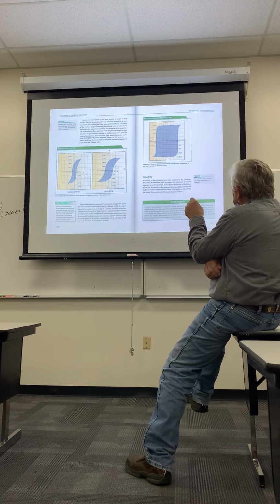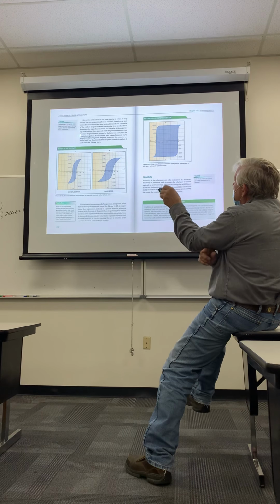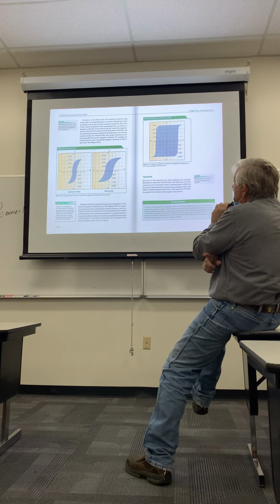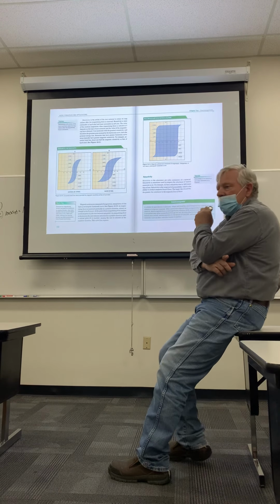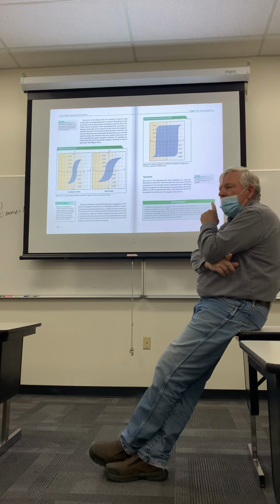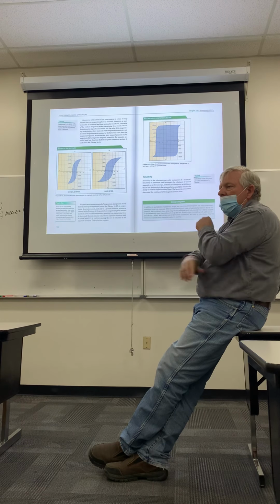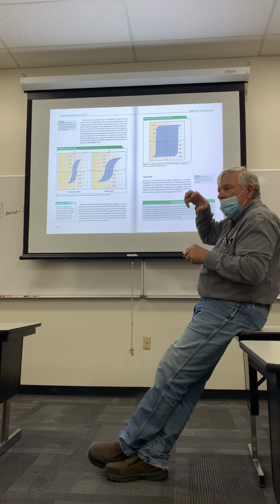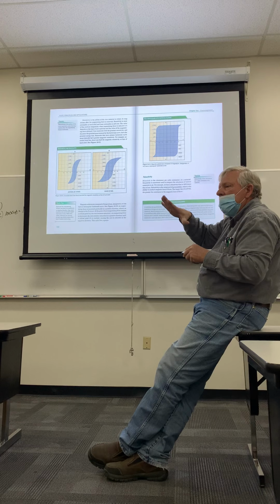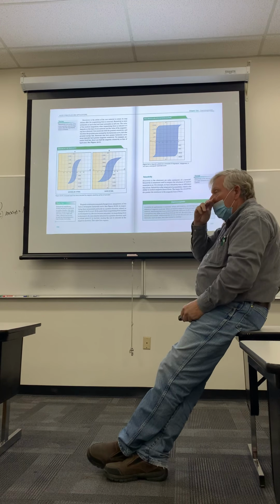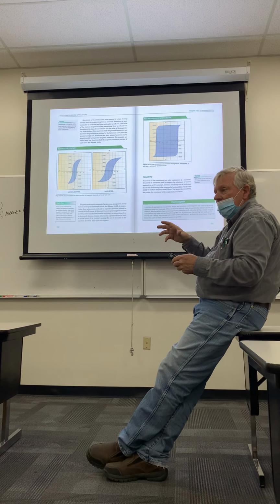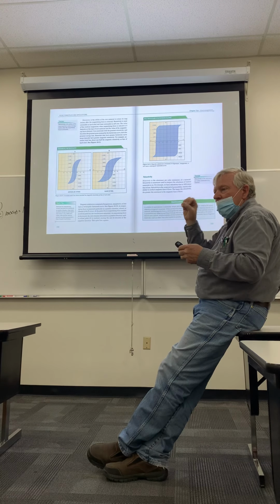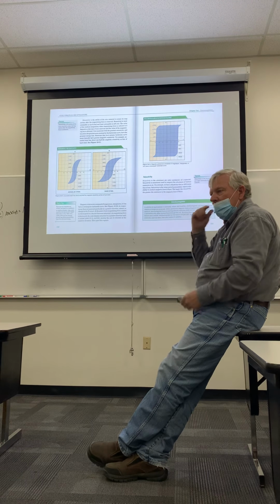So here is, you were talking about retentivity. Retentivity is the ability of the core material to retain its magnetism after the magnetizing force is removed. You see the word retain in there. So just think of retaining its magnetism. Some materials have high retentivity. They really hold on to their magnetic flux lines, and they reluctantly give them up. And then others are rather quick in their characteristic. They have low retentivity. They don't hold on to it at all. You shut it off and it goes right down. We're talking about seconds here anyway, or microseconds.